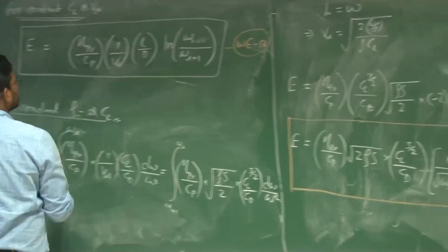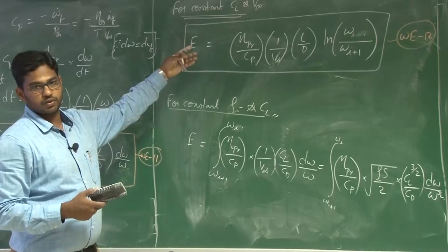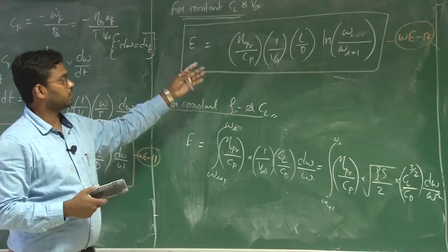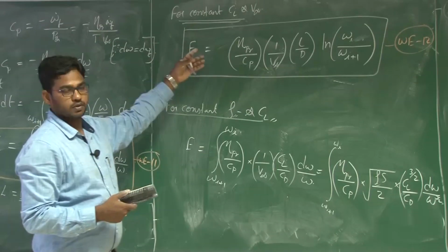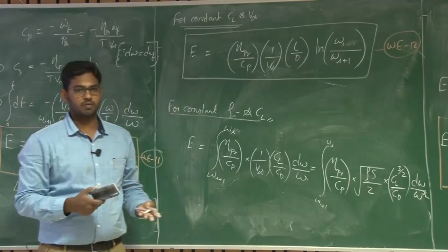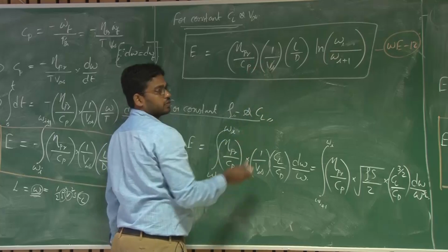Now, generally we consider this for initial weight estimation, that's why we get an estimate out of it with certain assumptions. With those assumptions we will get an estimate of the fuel load, which may be off by at least 20% of the actual value, right. So to start with, we can go ahead with these assumptions.